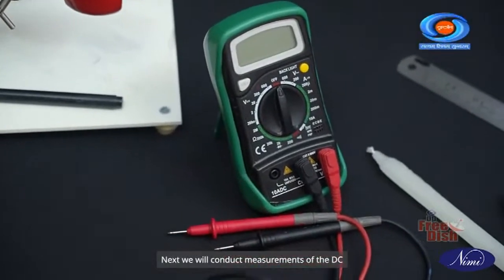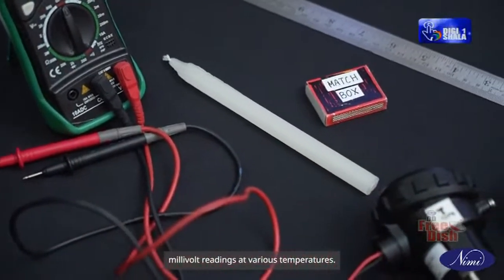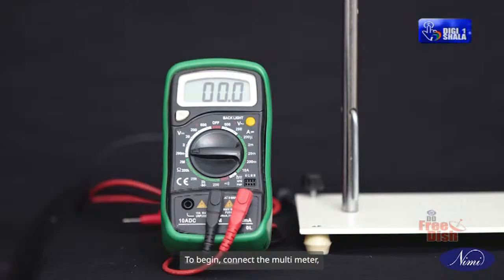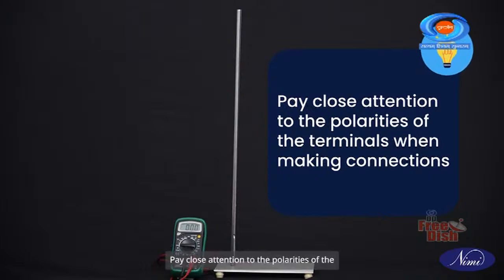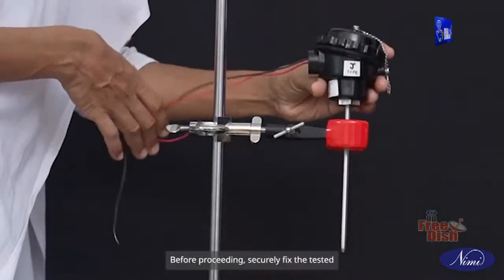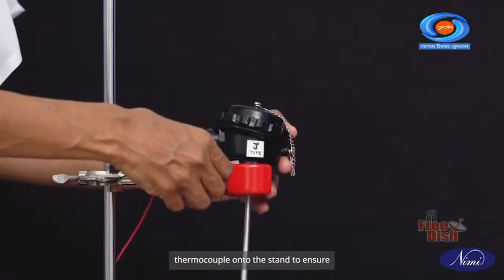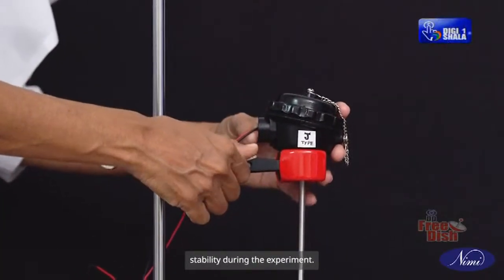Next, we will conduct measurements of the DC millivolt readings at various temperatures. To begin, connect the multimeter, initially set to the low DC millivolts range. Here is a safety tip. Pay close attention to the polarities of the terminals when making connections. Before proceeding, securely fix the tested thermocouple onto the stand to ensure stability during the experiment.